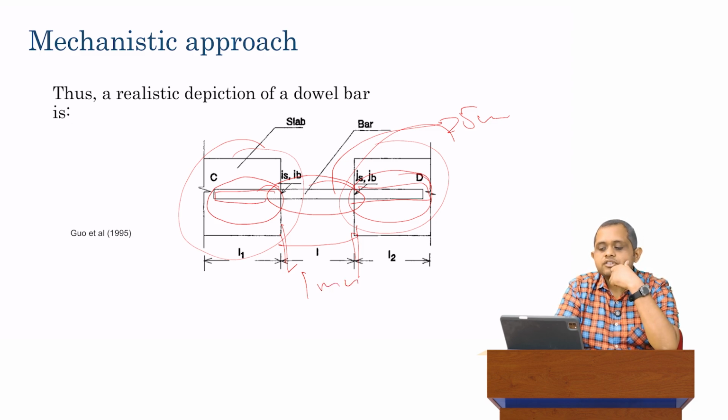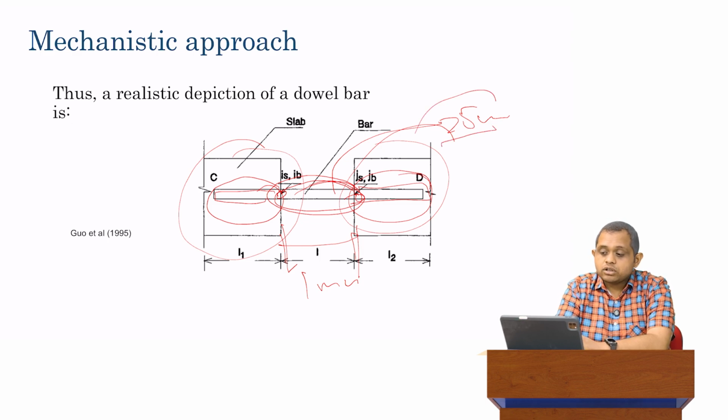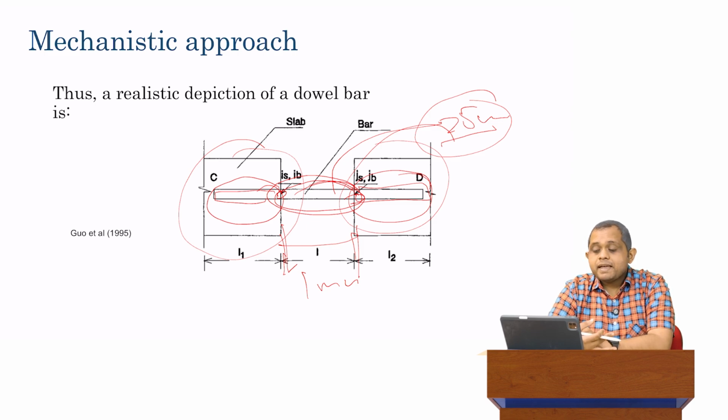So what we have is a situation where this overhang part, previously we were analyzing this overhang as basically an Euler-Bernoulli beam. But as we see, this is actually a beam whose length is much less than its cross-sectional dimension. Here the radius or the diameter is around 25 mm, but the length is only around 1 mm. So this is actually not an Euler-Bernoulli beam at all. It's only an Euler-Bernoulli beam if the length is much larger than the cross-sectional dimension. And that brings us to one shortcoming of what we are doing. Everything we discussed is mathematically correct, but it doesn't actually work out in practice because we are making a mistaken assumption about the physics of the system, that is assuming that it's an infinitely long Euler-Bernoulli beam.